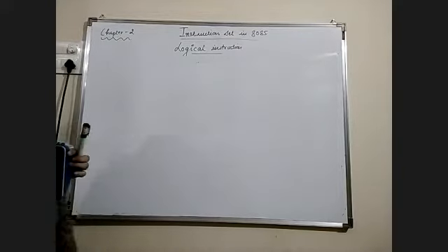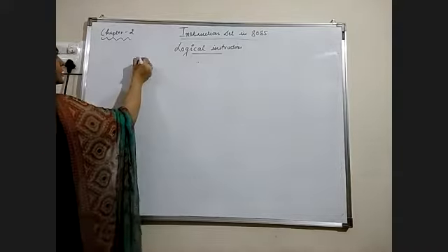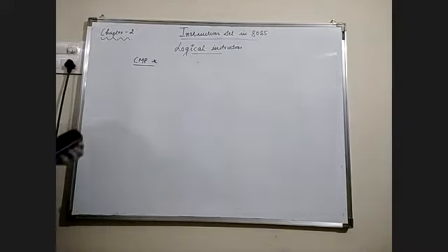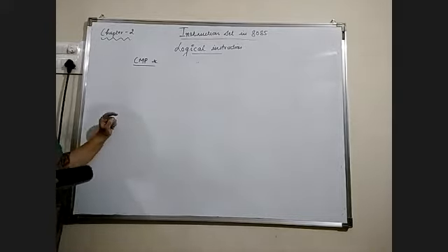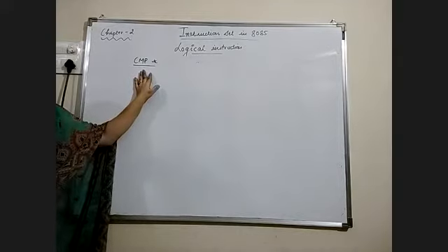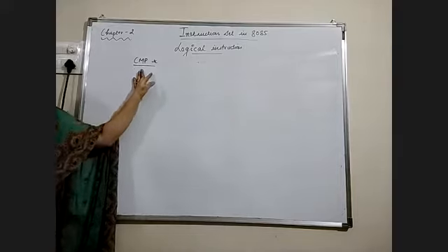Okay, so the next type of logical instruction we have under this group is CMP R. CMP R is the instruction we use if we want to compare the contents of the accumulator with the contents of a register. So basically, we can use this instruction for comparison.